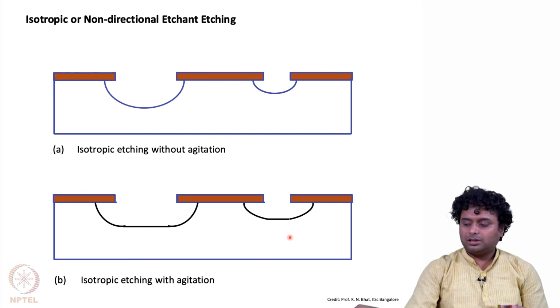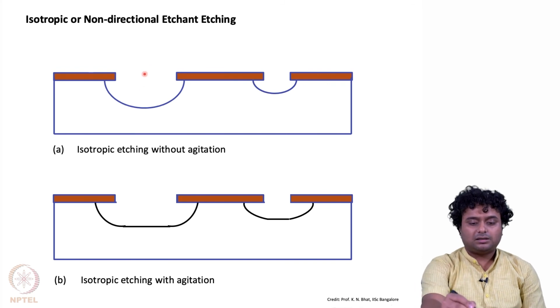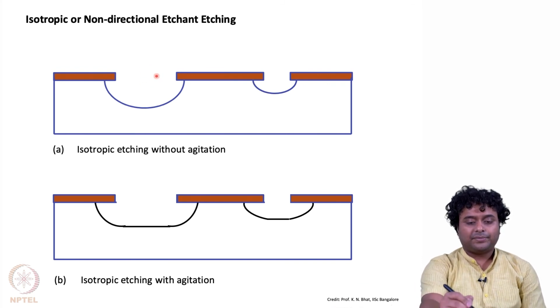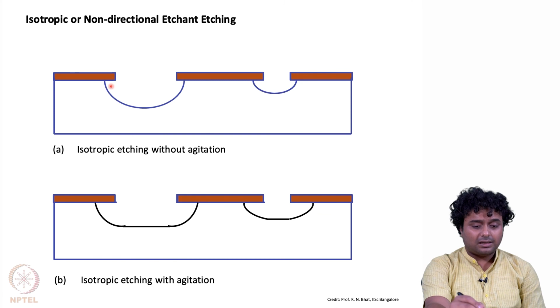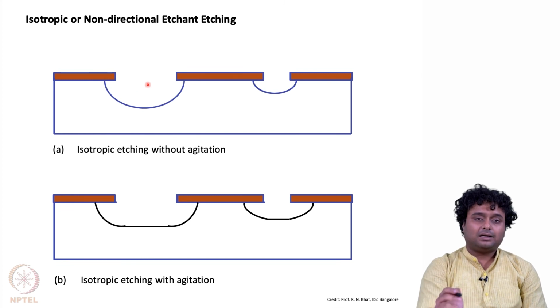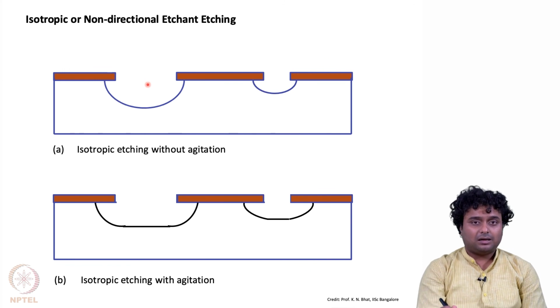Now if we put this material here, then this is the 100 direction, and this is another 100 family, whereas for 110 there will be this plane as 111, which will have the lesser etching rate. In that case it should have been that in one direction there is more etching and in another direction a different kind of etching, but that has not happened in this case, because HNO3 is such an aggressive agent that it easily reacts with silicon and completely etches it away in all directions.